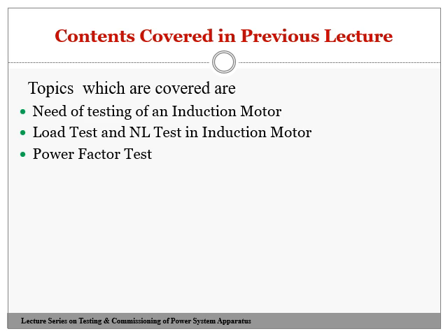Then afterwards, we came to know how to determine the power factor by different methods, that is, the load test. In the load test, we had the 2 wattmeter readings. Those 2 wattmeter readings can be used directly for the determination of power factor at which the particular induction motor will be operating, as we have seen in the previous session.